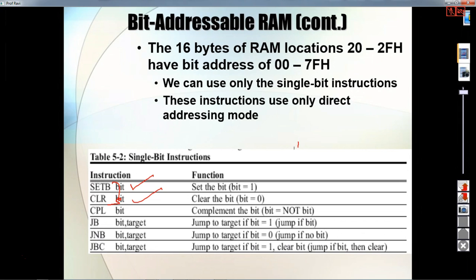If it is starting with 20, you can set or reset that bit. You can also use complement bit. If the bit is 1, you can jump somewhere else, jump if bit. You can also jump on carry. These are the instructions we can use.